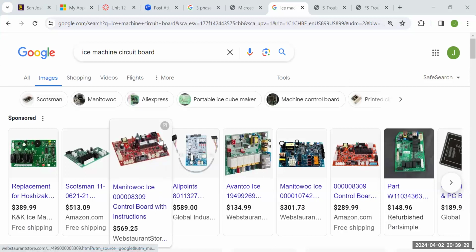I've fixed them to get them going. So I've taken a wire and soldered it from point A to point B on the back of a board to complete a bus line. But then I wrote on the paperwork, no warranty. This is a temporary fix. Because what will happen is once you get it running, sometimes they'll call your shop and say, I don't want the repair now, the machine's working fine. Well, I did a temporary fix. That's why it's working fine. That thing's not going to last very long. That wire could pop off, or it's not as solid as a new board would be.